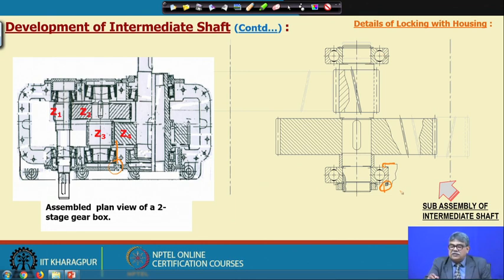On the other side, we simply make a straight cut, and this cover, which is shown here a little bit, will be shown in more detail later, but here there will be a gap. So, if there is extension or contraction of the shaft, it can move this way and that way, and this is called a slide fit. The housing bore on this bearing is made a slight slide fit. Here also it is kept a slide fit. Okay. So, I think this is now clear, but we can also make an alternative locking arrangement.